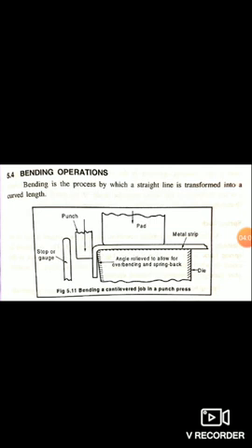The amount of bending depends on properties of the material, length of bend, condition of the cut edge at the end of the bend line, and direction of orientation of the axis of the bend to the direction in which the material was rolled.